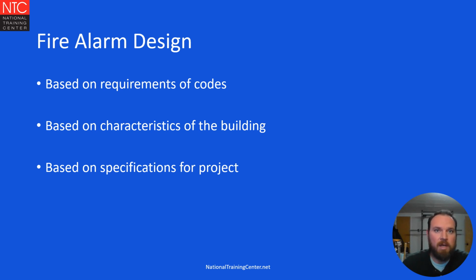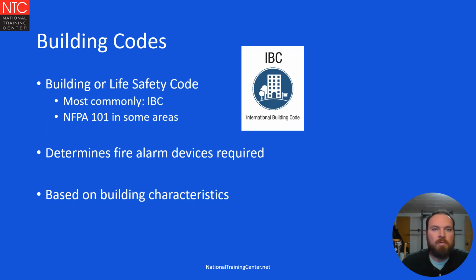These things combined is how a designer can take drawings of architectural nature and turn them into a fire alarm system. So let's get into it. First thing we take into account are going to be your building codes. With the building codes, you have options. Most common building code that's utilized out in the field is going to be the IBC. However, in some jurisdictions, some areas, NFPA 101 is used.